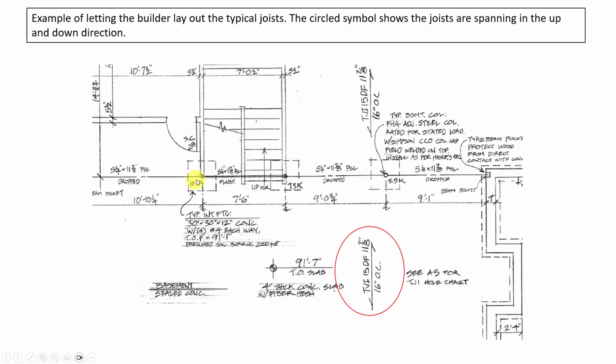So these footings are 30 by 30. Now in reality, I might be and have been able to get by with like a 24 by 24 or a 28 by 28. But it's not worth my time to size all those to save them 5 cents worth of concrete and make them form up a different size of footing for every one. So you size the worst case and they do them all the worst case, at least in this one.